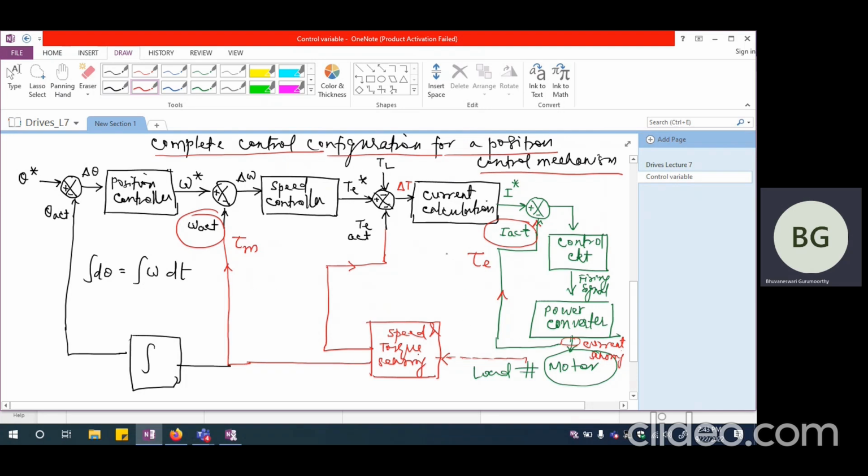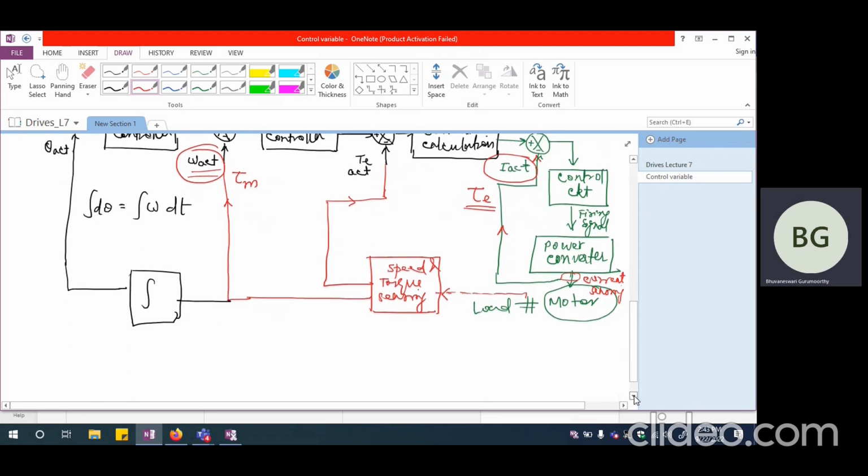So you may execute this current control loop 10 or 15 times before you get back to check whether the speed error has been nullified or not. So generally, this depends upon, again, the time constants of various system configuration. And this I mentioned in the last class also.